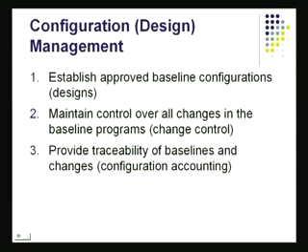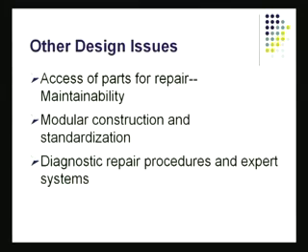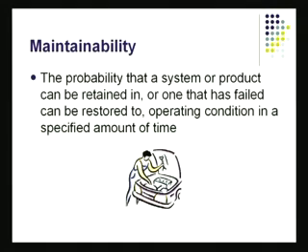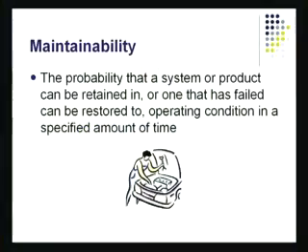And I've listed them out here. And I've listed out some more things. Other design issues also are there. For example, maintainability. That's a big, huge issue in design. If I put a system together, I should be able to repair it. I should be able to reach into the parts. So if you're trying to change an oil filter, for example, you should not have to hoist the car. You should be able to reach there and do it.